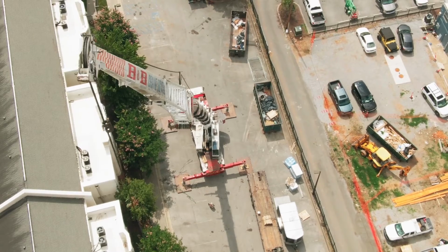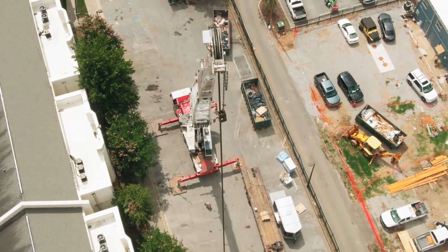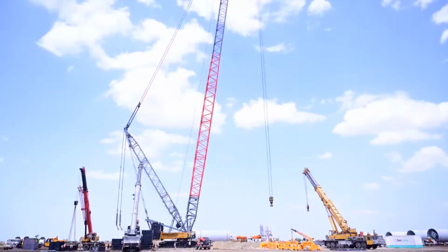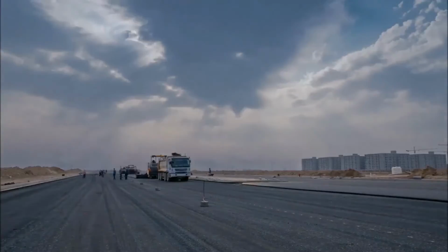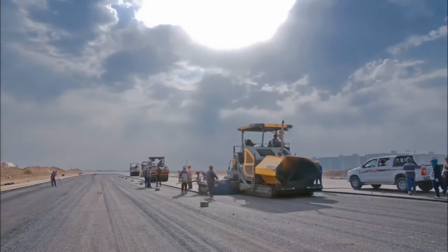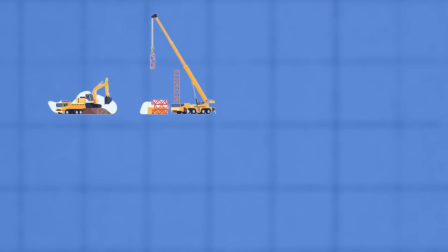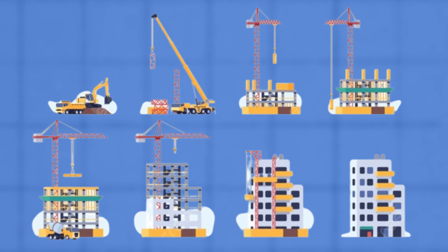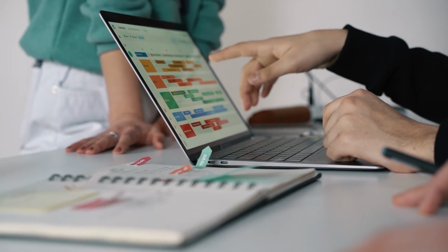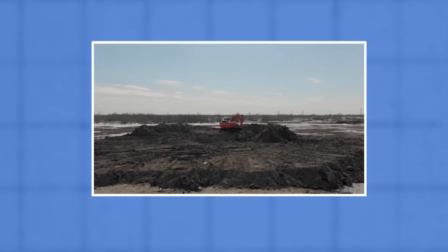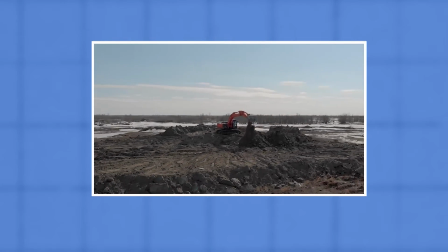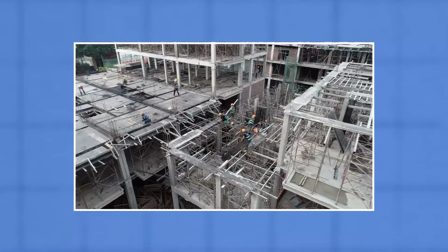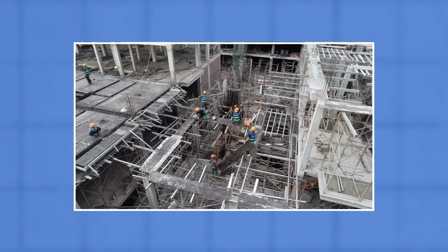When all the planning is done, materials are acquired, machinery is set up, blueprints are made, and the work team is selected. The next stage is the execution of plans made on paper into real work. This phase involves breaking down the project into smaller tasks. These tasks are then executed according to the project schedule. This execution phase includes activities such as site clearing, foundation laying, structural erection, installation of utilities, and so on, depending on the nature of the project.